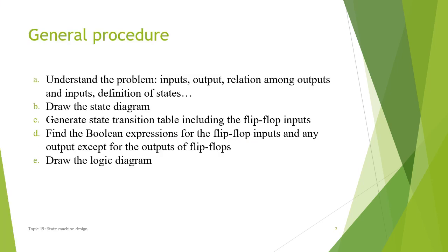First, let's look at the general procedures to design a state machine. Actually, if you read this, you will find it's not that different from the steps to design a combinational logic circuit. But there's still some difference here. After we understand the question and figure out the input and output, we also need to figure out what type of state machine we're going to use, how many states we need, how many flip-flops, right? And then we need to draw the state diagram.